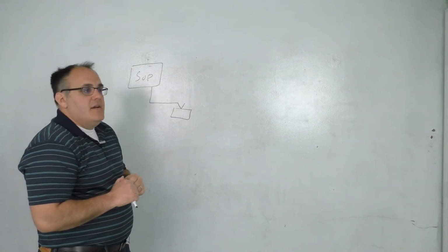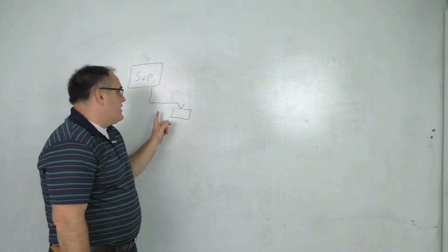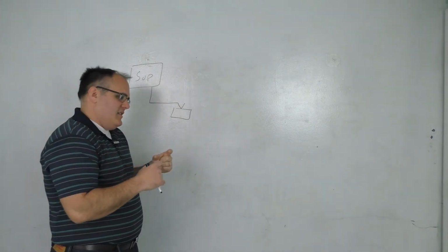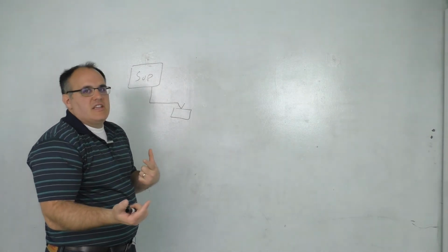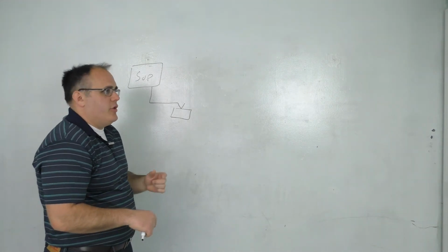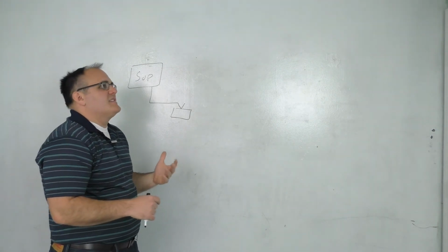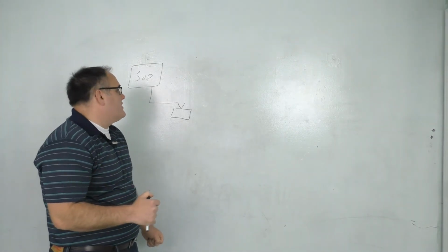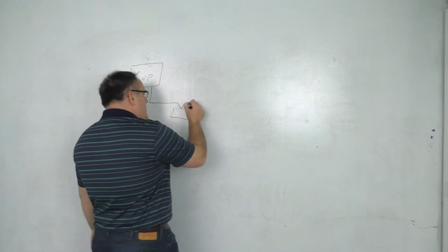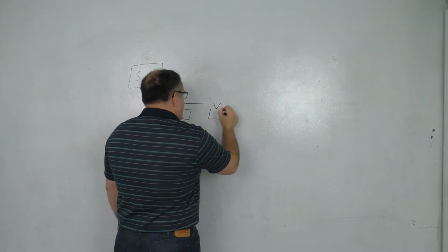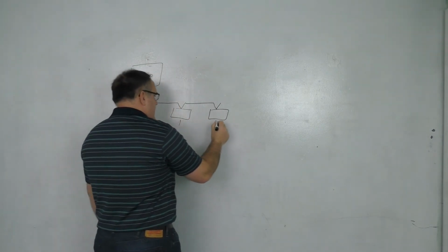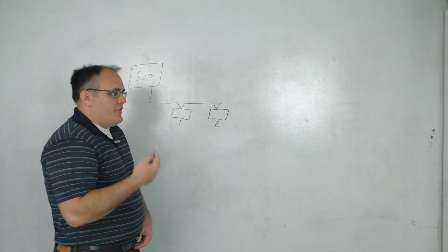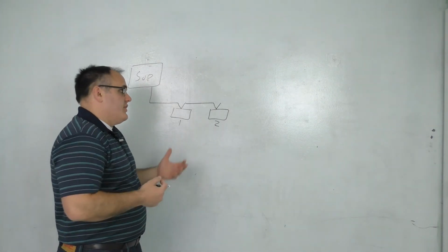I recommend that you include a kind of legend that shows them how to use the dip switches if you haven't worked with this installer before, because that can be a little confusing, and there's nothing as fun as going back into the ceiling and readdressing everything. That's super duper awesome. Not really. With that being said, we address our devices, okay? So address 1, address 2. We've got our device IDs that are unique for our devices. Those aren't set by the installer, that is set by the commissioning or the setup person.